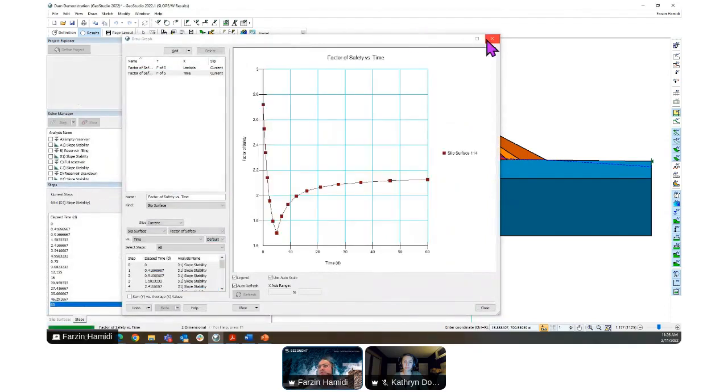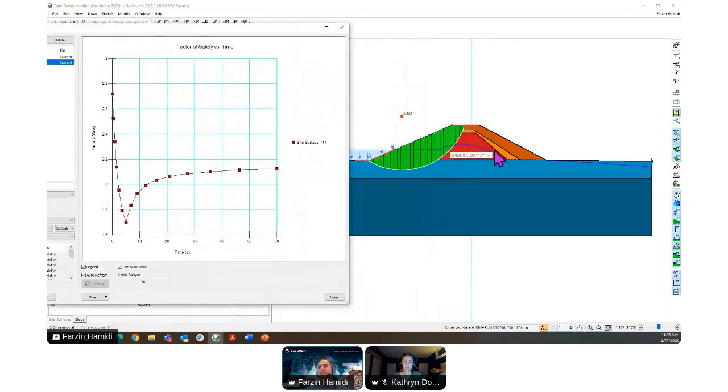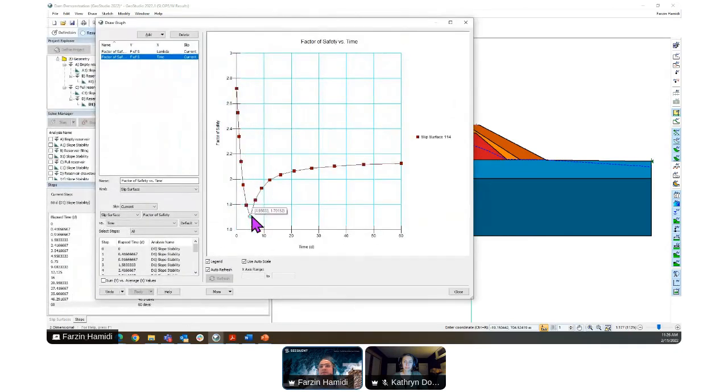So I'm going to show you how we did that. You can see the evolution of the water over time in a graph view, perfectly shown in the GeoStudio interface, and you can easily export this graph and play with it if you are interested, as a CSV file, by just right-clicking on the graph, and you will be able to change the units.